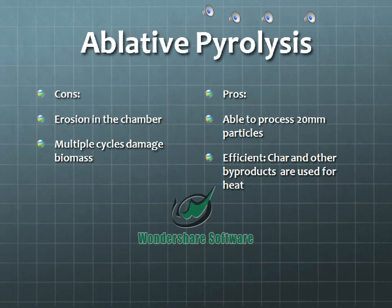The advantages of the process are that it can use particles up to 20 millimeters in size, which is much larger than other means of production can support. This will be helpful in the mass production of BioOil. In addition, there is hardly any waste in production. All of its byproducts, such as char and gases, are used to heat up the vortex reactor. Essentially, the only product of the process is BioOil.